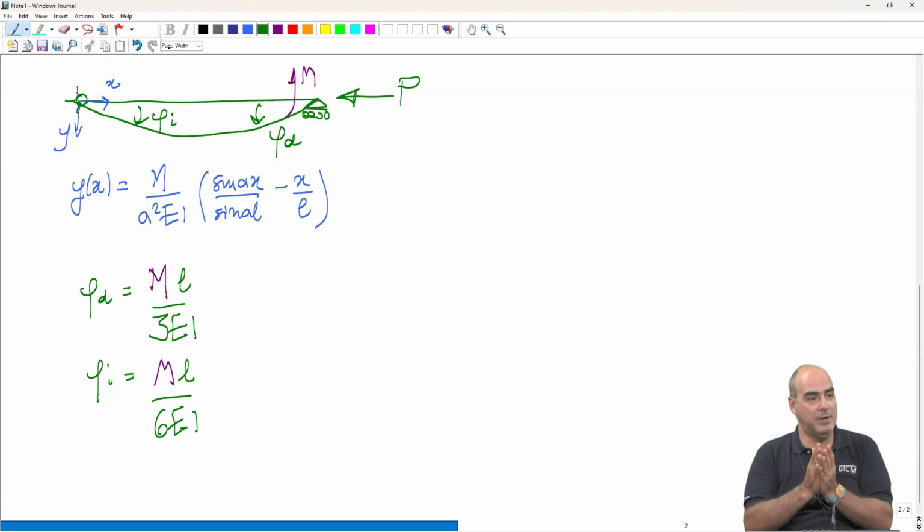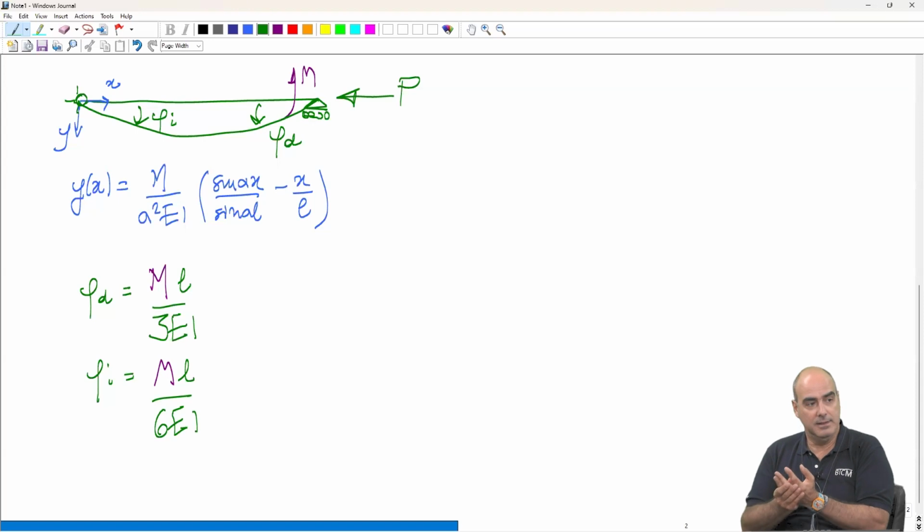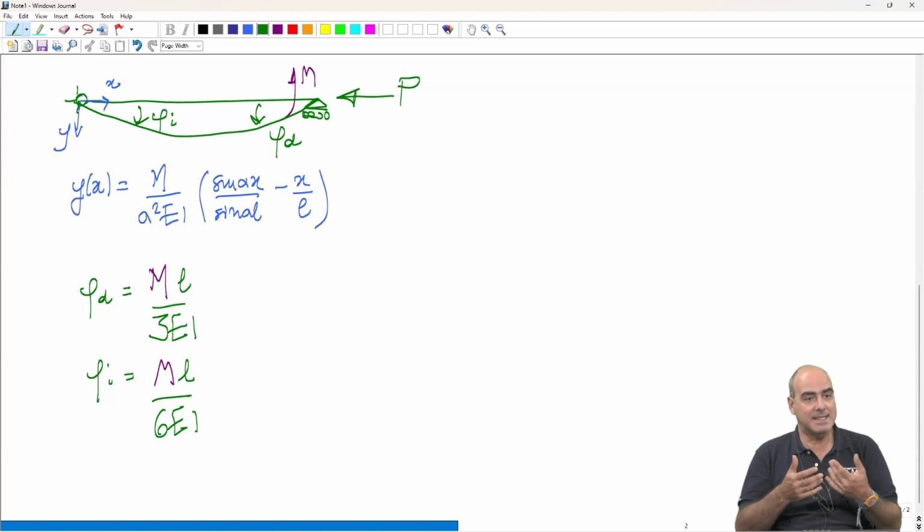So if I calculate a rotation, then my connection must allow that. Because if I have a certain amount of rotation and my connection at a certain point does not allow it anymore because it opposes in some way, you will have a parasite action.